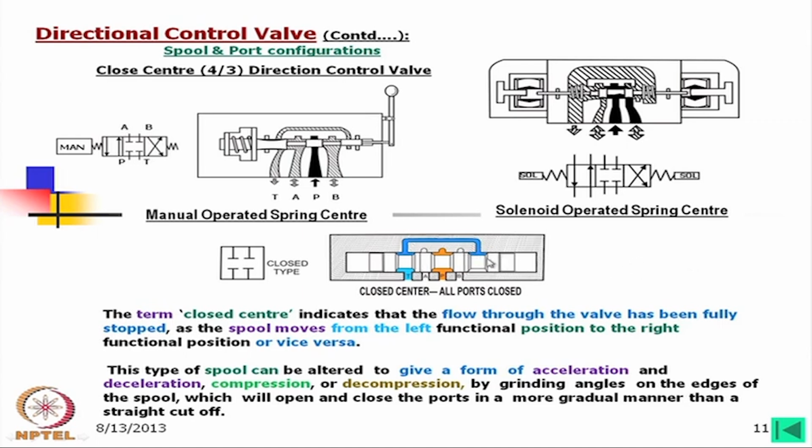Rather we change the design of the edge. Now, if we provide these chamfers or make it round, then the port will open and close in a more gradual manner than a straight cut off, and sometimes it is essential, because the straight cut off will give a shock to the system.